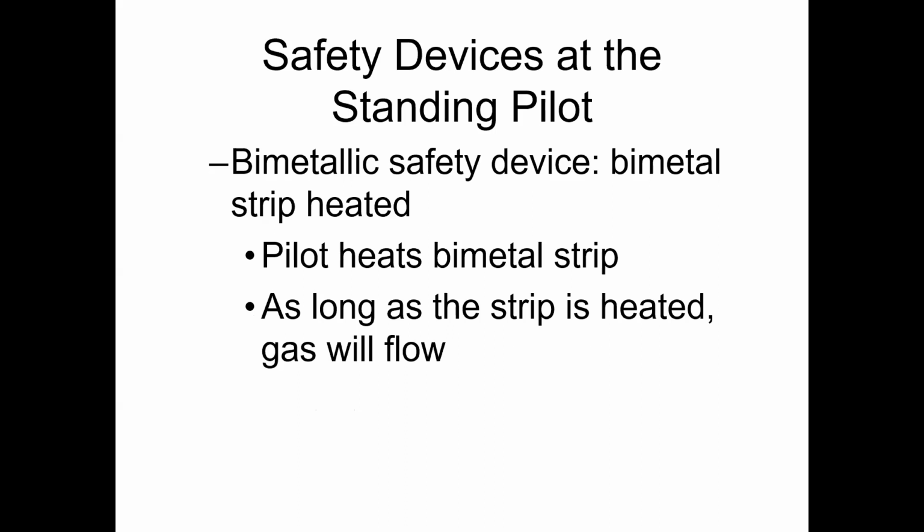As that bimetal is heated, it's going to warp that metal, all right? This has it so when the pilot flame is lit, you're going to have a bimetal strip complete a circuit. It's going to close a circuit and tell the system, yes, now that I've completed power, I'm going to allow for power to pass, or now that I've completed a flame, I'm going to allow for power to pass through this bimetal safety device and keep this gas valve open for the pilot so that it continues to have a flame. This is a really nice device because it doesn't have to be directly in the flame.